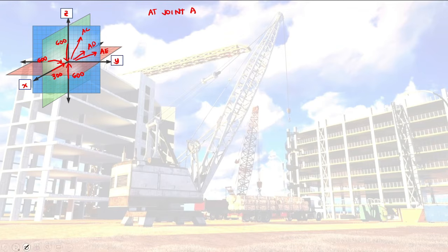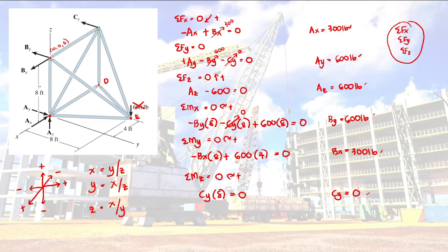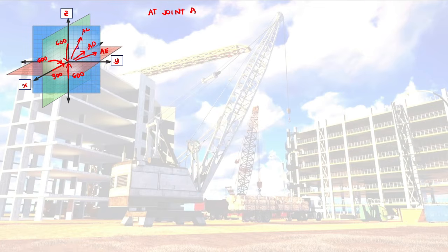So, for the components, let's use the slope triangle. Bakit hindi tayo mag-XYZ? Kung mapapansin nyo, yung AC natin, nasa plane ng x-axis, correct? So our slope triangle here would become, say this one is 8, then this one is also 8. So the slope triangle would be 1, 1, square root of 2. So we have a vertical component here of 1 over square root of 2 AC. Then we also have here 1 over square root of 2 AC.